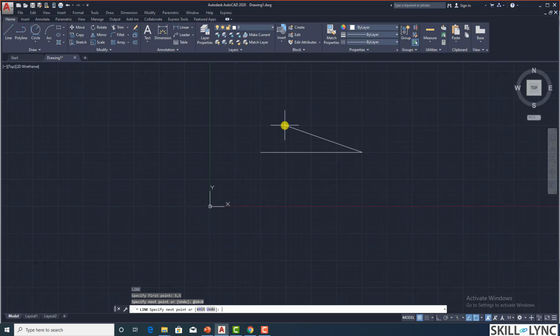and now again the next one. The incremental distance is going to be 5, and then the angle is going to be 90 degrees, that is upwards. So you specify 90. And now again @. Now the distance we require is 10, and now the angle, you have to go from right to left, so it's actually the other side, so it is 180. Going on a polar coordinate system, the angles are 0, 90, 180 and 270. So we have specified @10<180.